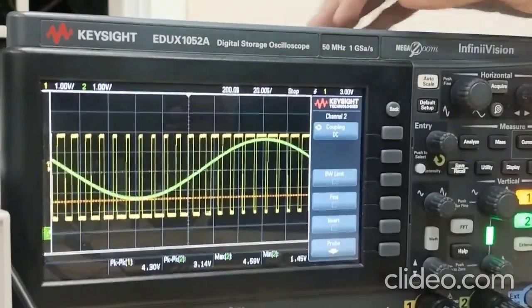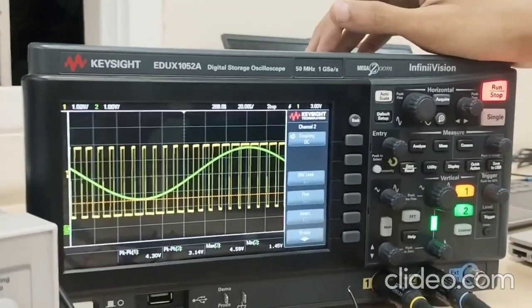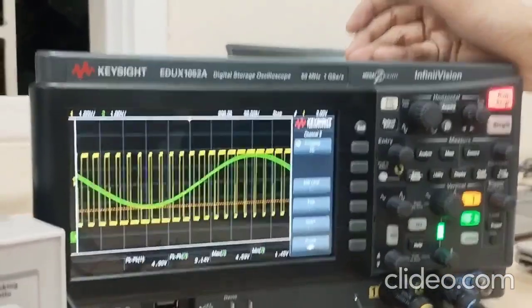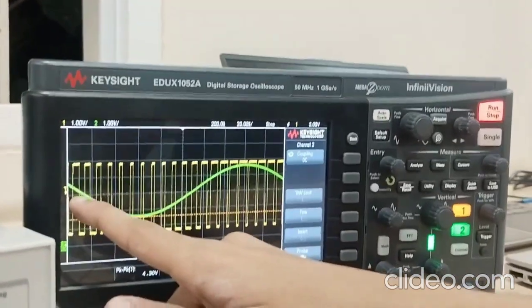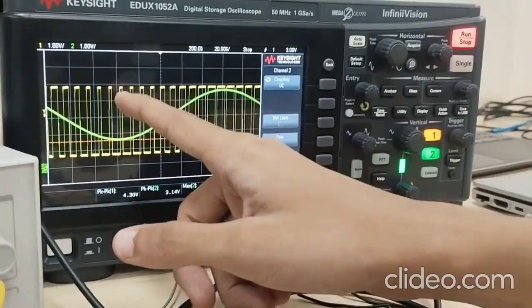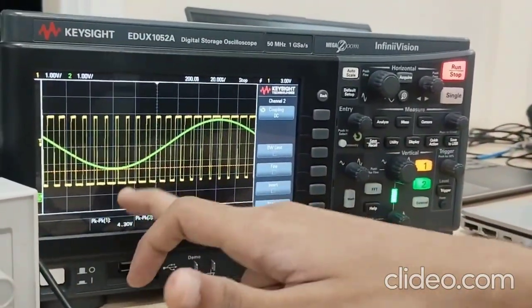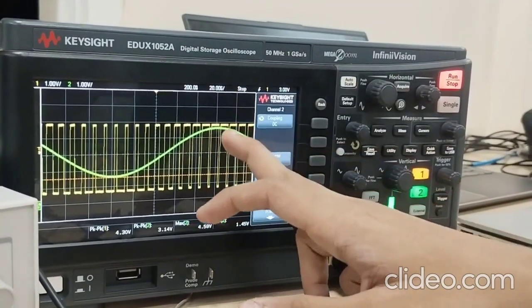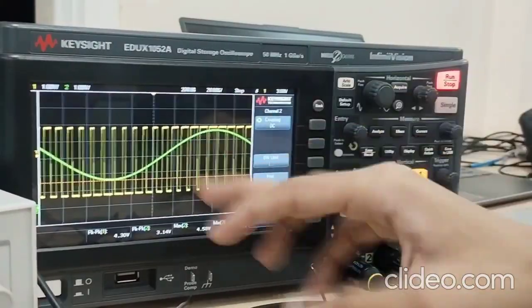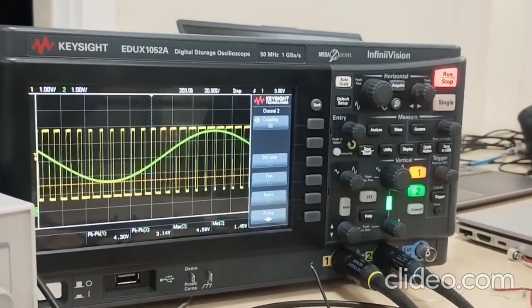And here we provide a visual representation of how the PWM signal works. As you can see, wherever the input signal amplitude is lower, the duty cycle, or the on time of the PWM wave, is less, and wherever the signal amplitude is high, the duty cycle is higher, or there is more on time. And this is the basis of the PWM signal.